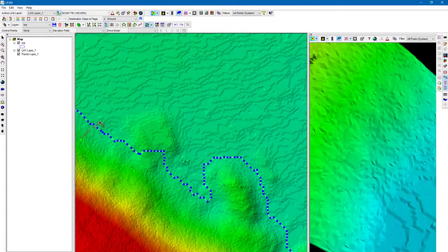So because I started here, I'm left clicking. The areas that I'm left clicking, I'm basically creating a new extent for the stockpile toe. So it's going to remove this little section here, and then it's going to be replaced by the shape that I'm drawing right now. I have Auto Z on, so it's going to conflate to the surface. Let me go ahead and finish clicking here.